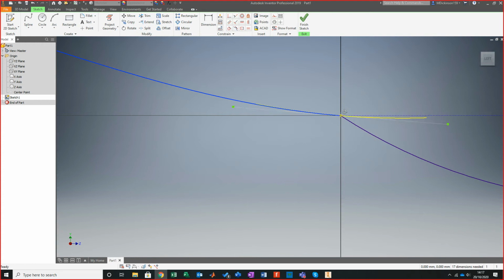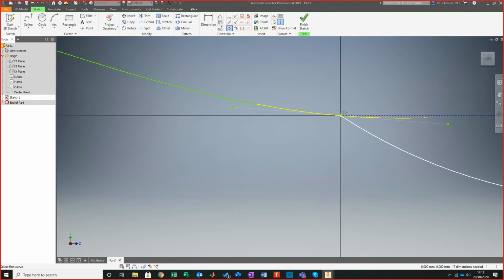So, look at the constraints. We've got all the selections that we need. Now, under tangent, it's literally saying, as you'd imagine, as you've had to listen to for years and years on end, give me a tangent marker to operate to. So I select my spline, I select my 3-point arc, okay, let's just put it on there.